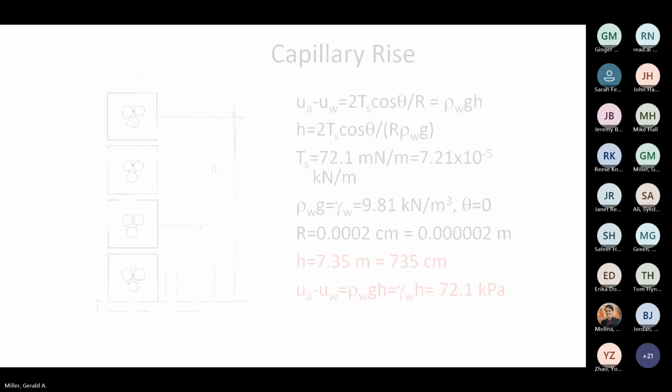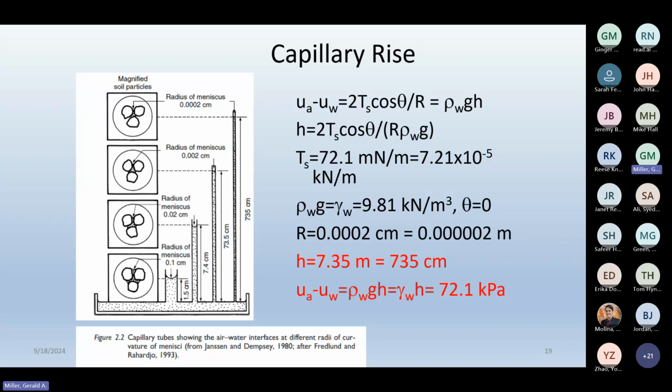And so here's an illustration of capillary rise in soils having different pore sizes. And capillary rise, as we know, occurs in natural soils, right? That's the capillary fringe above the water table. Capillary rise is also associated with the development of frost heave. You get a zone of capillarity below the ice lenses that feeds into them. So it does occur, and it tends to be much higher when you have a much smaller pore size. Okay, so next thing we're going to talk about, any questions?